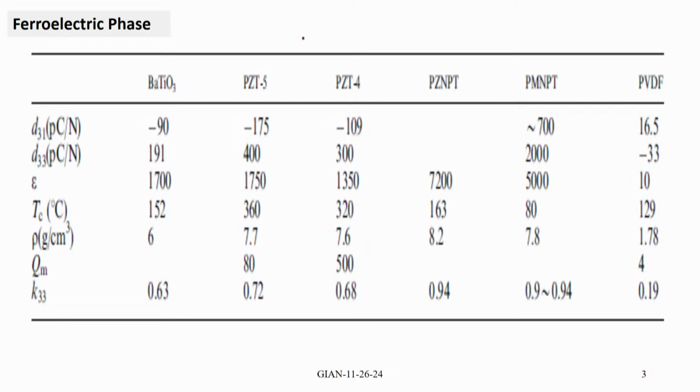and they can have very differing properties. PZT usually has a Curie temperature well above room temperature, above 300 degrees Celsius. The relaxor ferroelectrics, both PMN-PT and PZN-PT, have pretty good d33 values and very high dielectric constant, but very low Curie temperature compared to PZT. So for anything to do with high temperature applications, the relaxor ferroelectrics are not the ones you want to use.